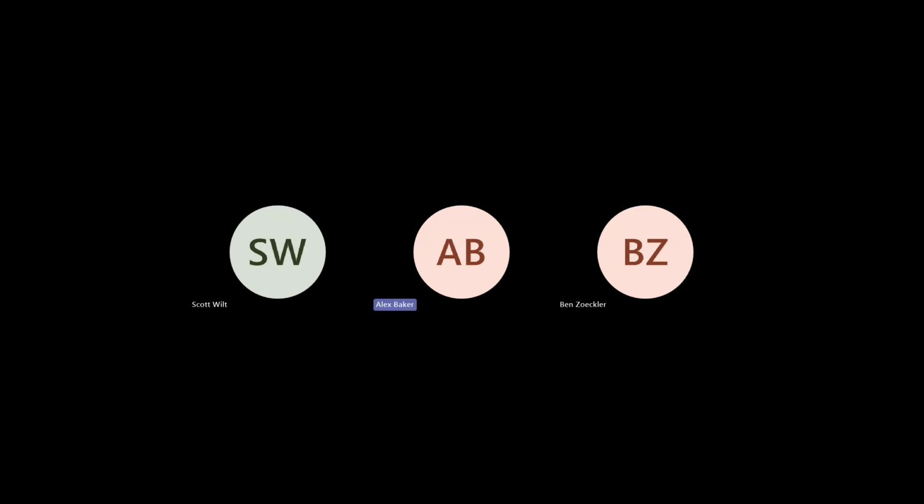Ben, you asked, can Moldex3D show the 3D tool temperature over the duration of the molding cycle? Yeah. When you run the analysis, your time step outputs will dictate the resolution of the animation that you'll get.